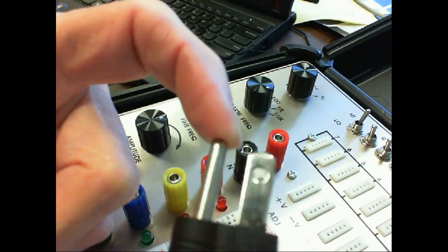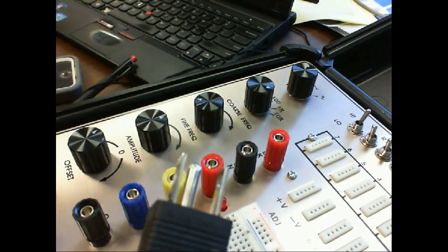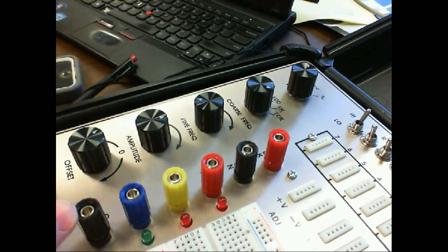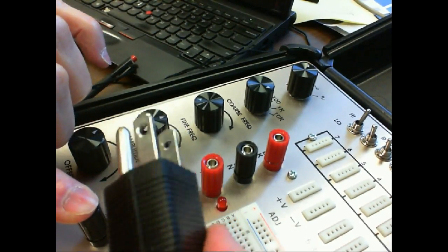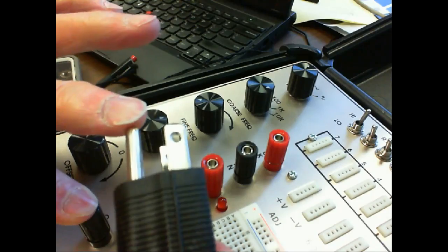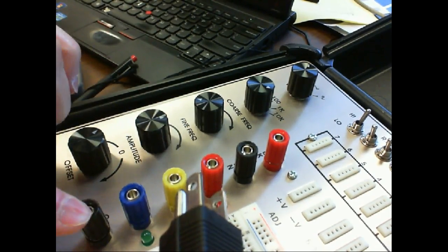It should be if you don't cut it off, right? Or the plug's not wired right. This is not connected to earth ground. This goes to a transformer. So that means if I took an ohm meter and measured between here and here, it's not going to measure zero. It's going to measure infinity. So that means this guy right here cannot be ground, right?